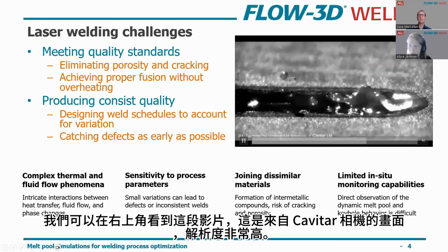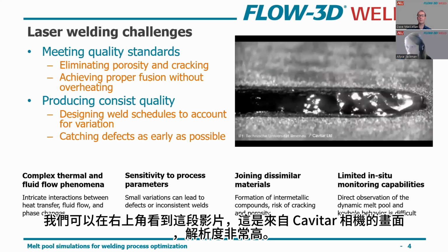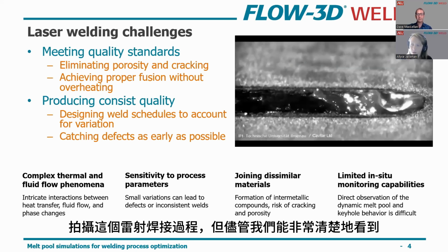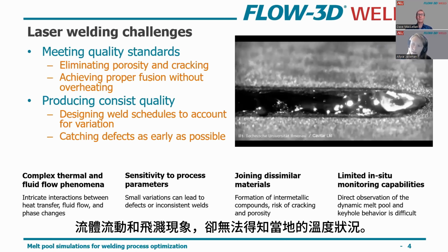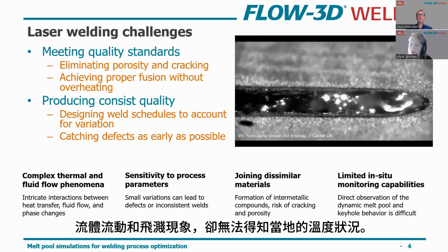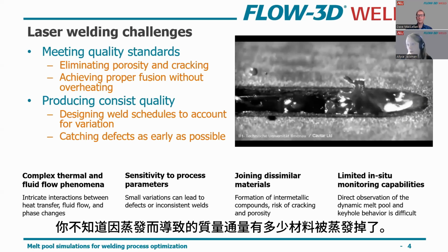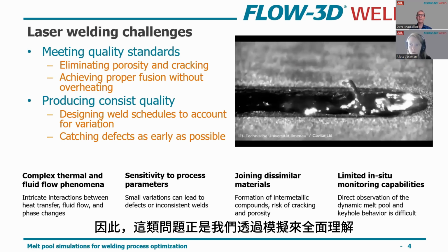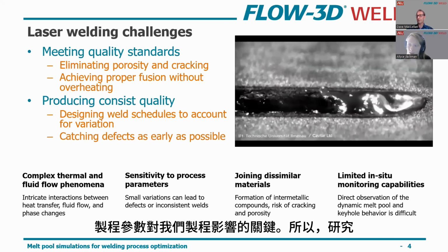So we can see in this video on the top right, this is from a Cavitar camera, very, very nice high resolution capturing of this laser welding process. But despite the fact that we can very clearly see the fluid flow, the spatter, you can't get an indication of what the local temperatures are. You don't know what the thermal gradients are. You don't know where the solidification front is. You don't know what the mass flux due to vaporization is, how much material is getting evaporated. So these types of things are where we look to simulation to really understand more holistically what the implications of process parameters are on our process.